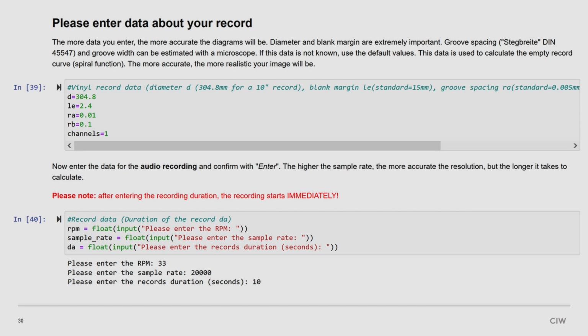And the third one is the record duration. If in 10 seconds my sample rate is 10, I get 10 measurement points in 10 seconds, so 1 per second. So you cannot make a sound of it. I need a lot of points, enough to have a nice pattern.